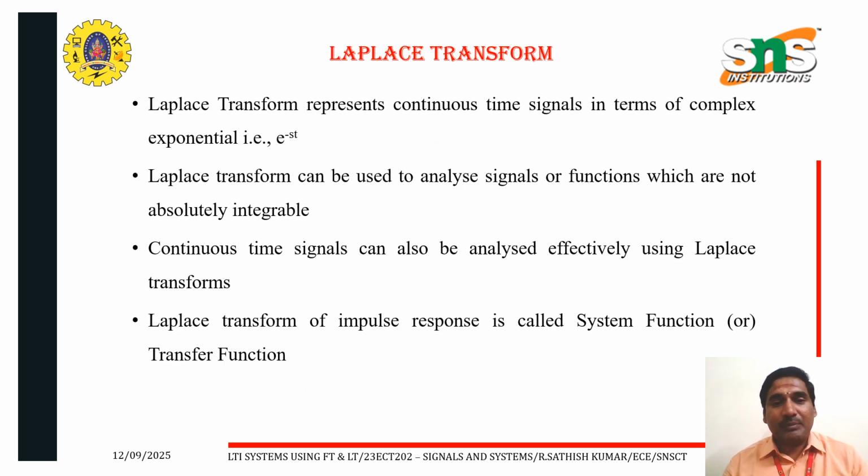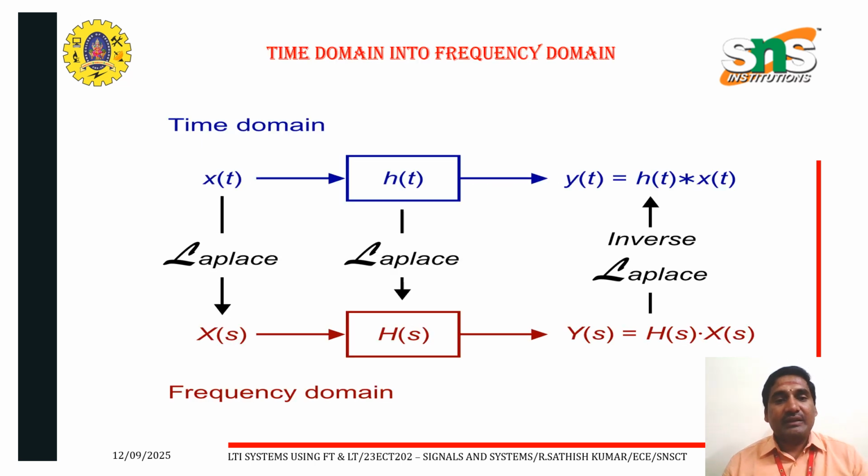Laplace transform. Laplace transform represents continuous time signals in terms of complex exponentials, that is, e power minus st. Laplace transform can be used to analyze signals or functions which are not absolutely integrable. Continuous time signals can also be analyzed effectively using Laplace transform. Laplace transform of the impulse response is called the system function or transfer function. This is time domain into frequency domain.